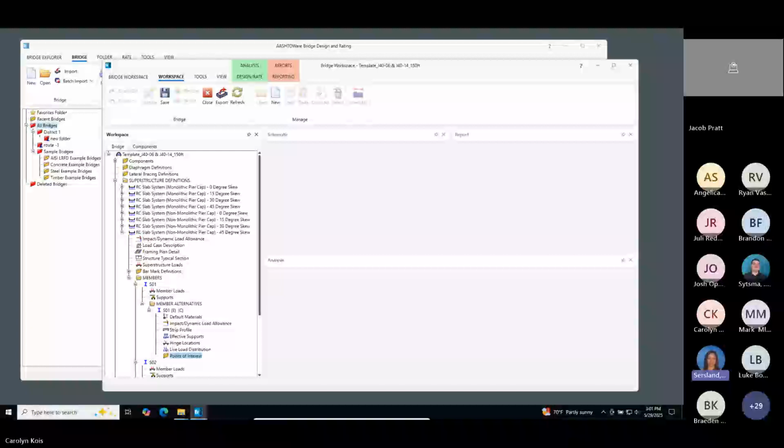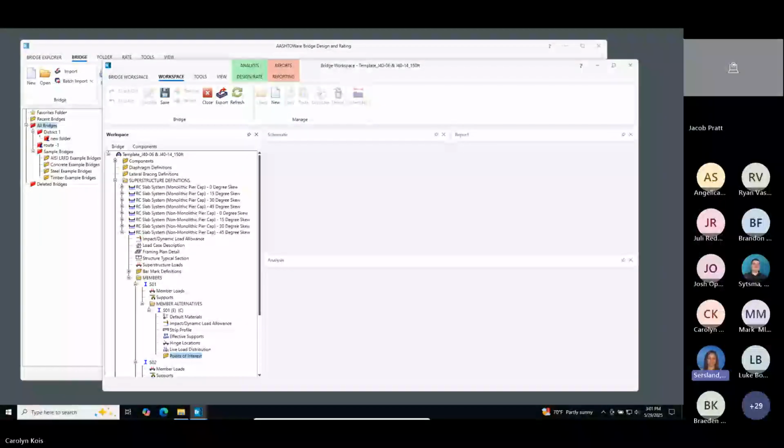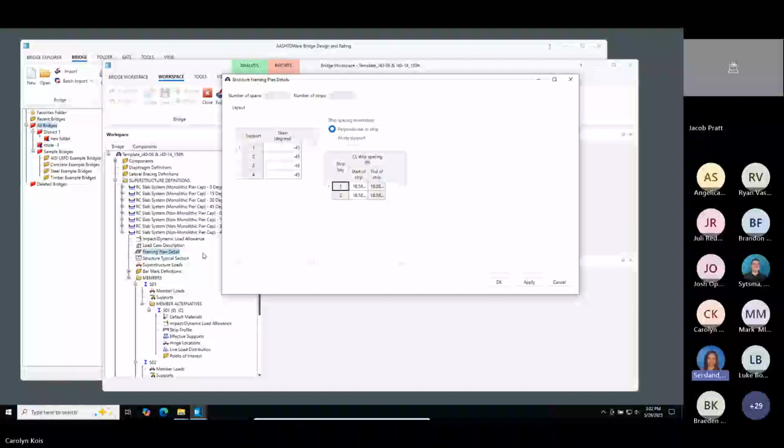Two other things I want to add about slab templates. Some standards have an option with a sloped bottom or a flat bottom. We went with the sloped bottom. Also, for LRFD, we did do all skews, but for LFD, we only did the zero skew. But I think for slabs, it's very easy to change the skew since we don't have any transverse reinforcement or anything. So those are just some things particular about the slab templates I wanted to bring up.